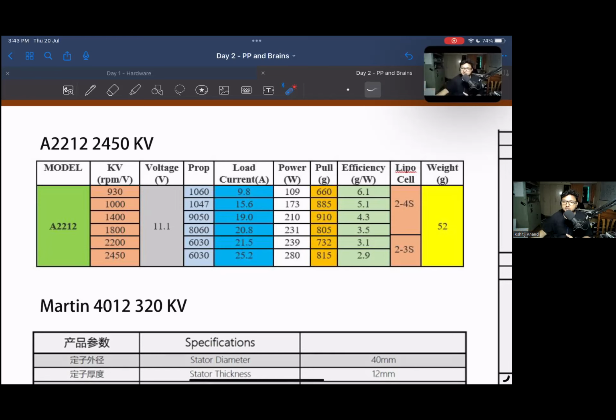I'll just refresh your memory. Yeah, three, exactly. Very rarely will a LiPo cell give you a different specification, but it has almost become a standard that all LiPo cells have somewhere between 3.7 to 4.2 volts, and the capacity that each cell has is roughly 2800 to 3600 mAh. So 11.1 volts means three cells.